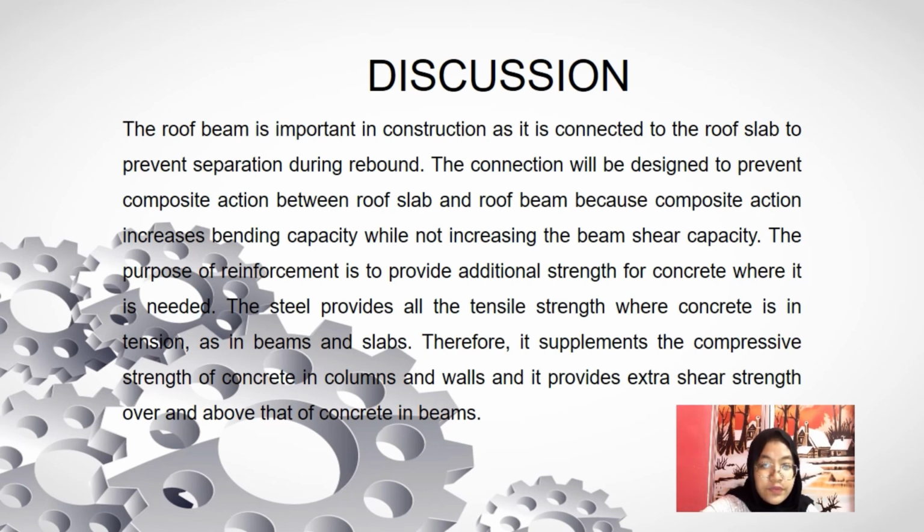The purpose of reinforcement is to provide additional strength for concrete where it is needed. The steel provides all the tensile strength where concrete is in tension, as in beams and slabs. Therefore, it supplements the compressive strength of concrete in columns and walls, and it provides extra shear strength over and above that of concrete in beams.